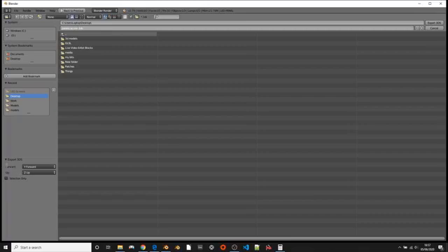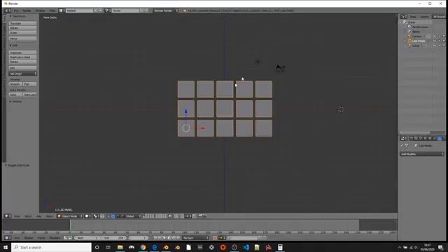Now here we can change our axes, the default axes. So I'm going to do that, and I think we want up, we want our Y up. Forward, I'm just trying to think if we want Z forward or minus Z forward. I'm going to go for minus Z forward. If it's wrong, it's wrong. We'll know for next time. Okay, so we're going to export 3ds like so. So all I want to do now, I just want to split this one up into multiple panels as well, because that's quite a useful thing to do there.